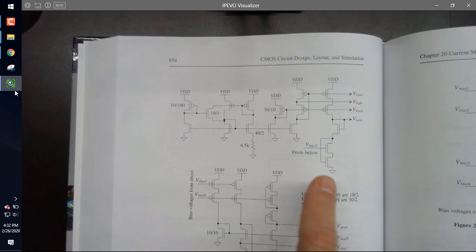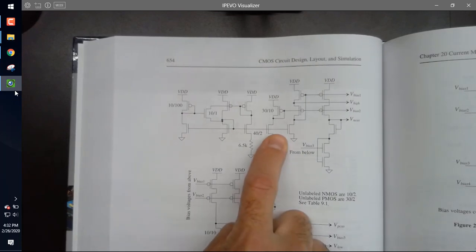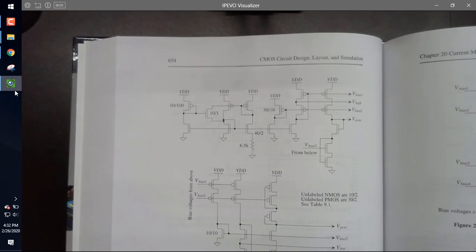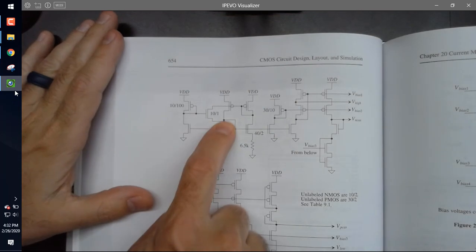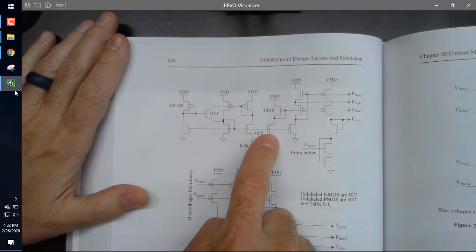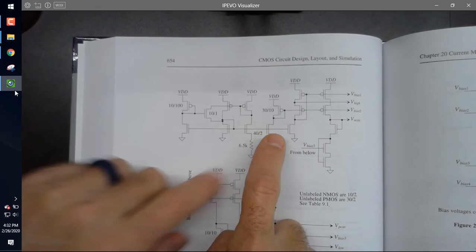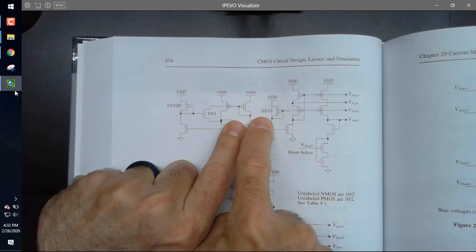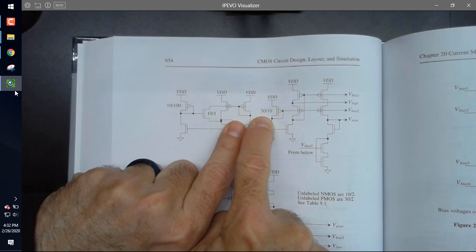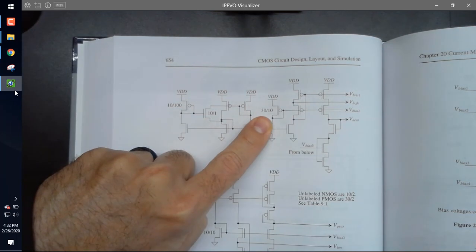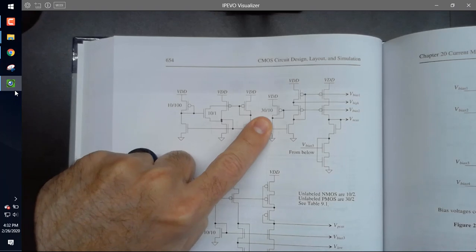All right? So what are these two transistors right here? They're NMOS, but I mean, what do they do? They're transistors too. They have a different W/L, so they multiply. Here's your gate-drain connected one in the beta multiplier. They're current mirrors. They provide the bias, and in this case, they provide the bias for a long L device and a wide swing cascode that's configured as a gate-drain connected transistor. Okay, so let me pause.